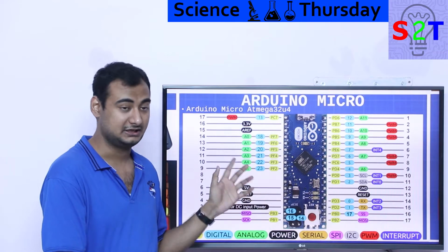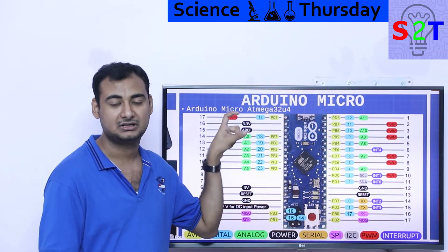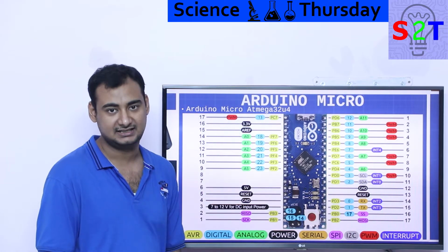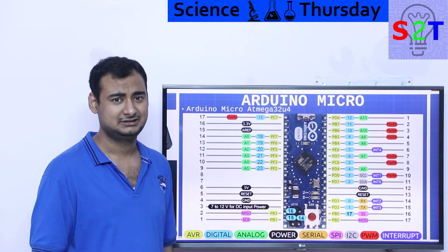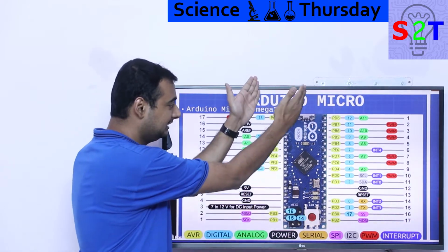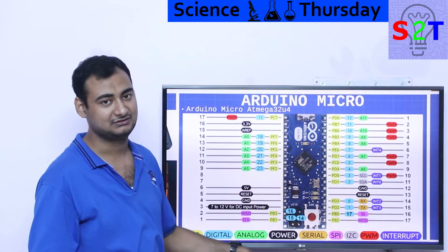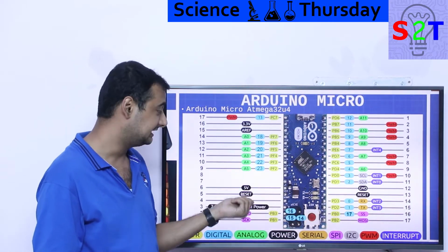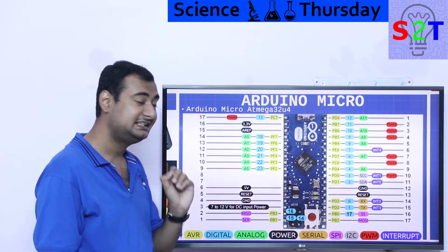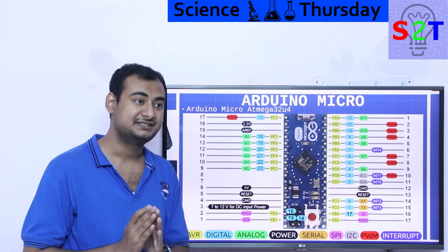And this is the whole reason I'm saying not to buy the Pro Micro. While they have the exact same microchip, the pin count is less. Simple fact. And both of them generally cost almost the same. Basically, Pro Micro is just the Micro with the last 4 pins chipped off. That is why I generally recommend the Arduino Micro. It has more pins, flat out 20 digital input and output pins accessible.